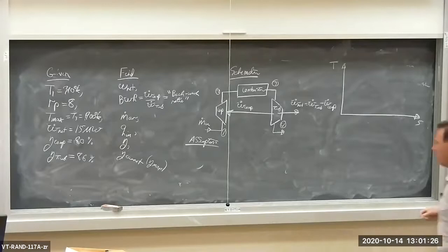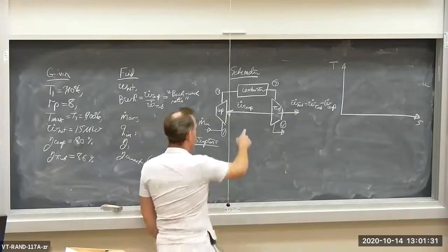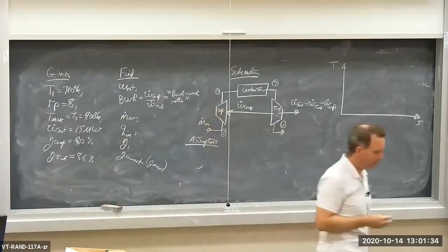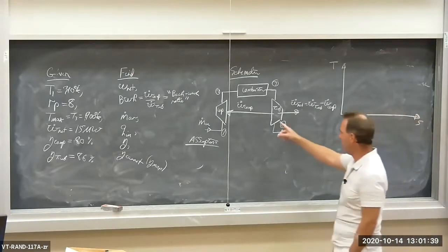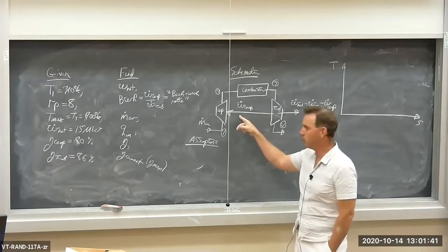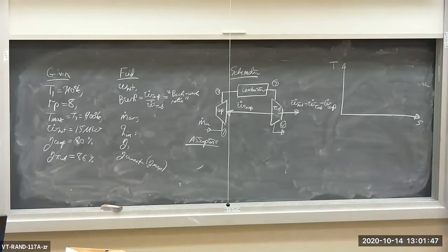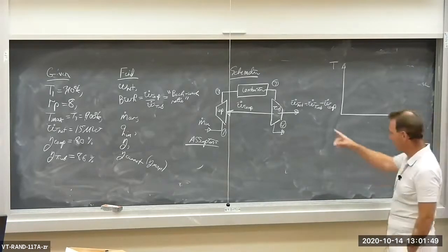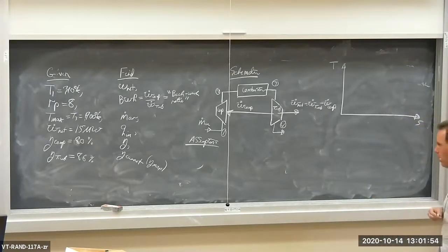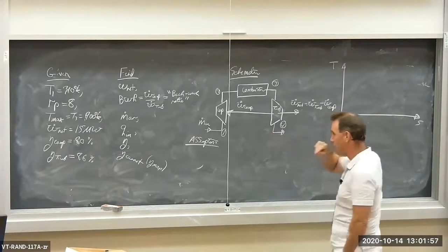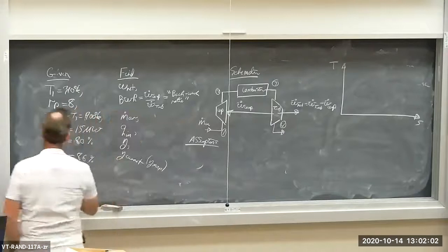So remember, the Brayton cycle utilizes a compressor which compresses the air, a combustor where the heat addition occurs, perhaps isobarically, perhaps not, and then work is extracted by the turbine, and some of that work or power is used to drive the compressor, and the remaining, or what is left over, if we subtract the compressor power or specific work, is the net work produced or net power produced by the gas turbine. This whole thing is the gas turbine. So let me put up the TS diagram here. Well, let's go over the givens first.